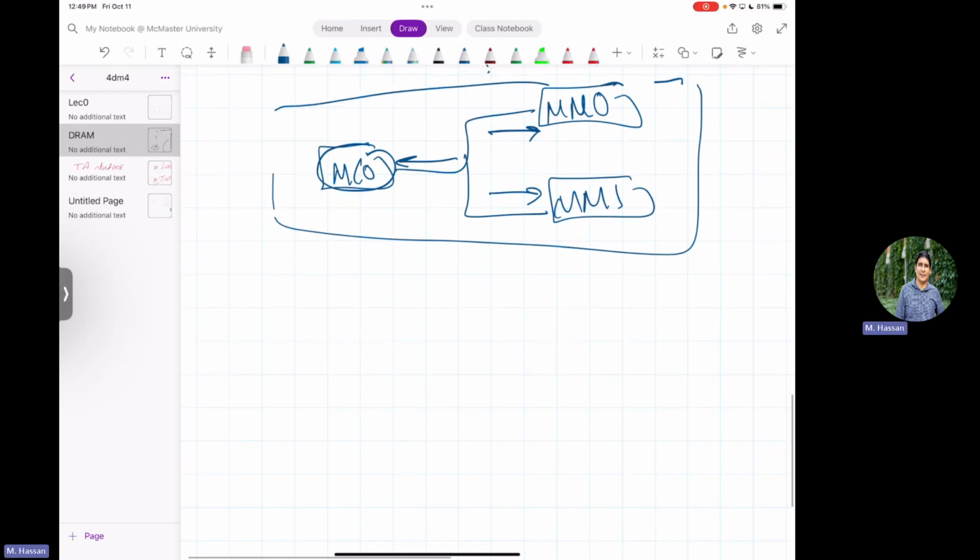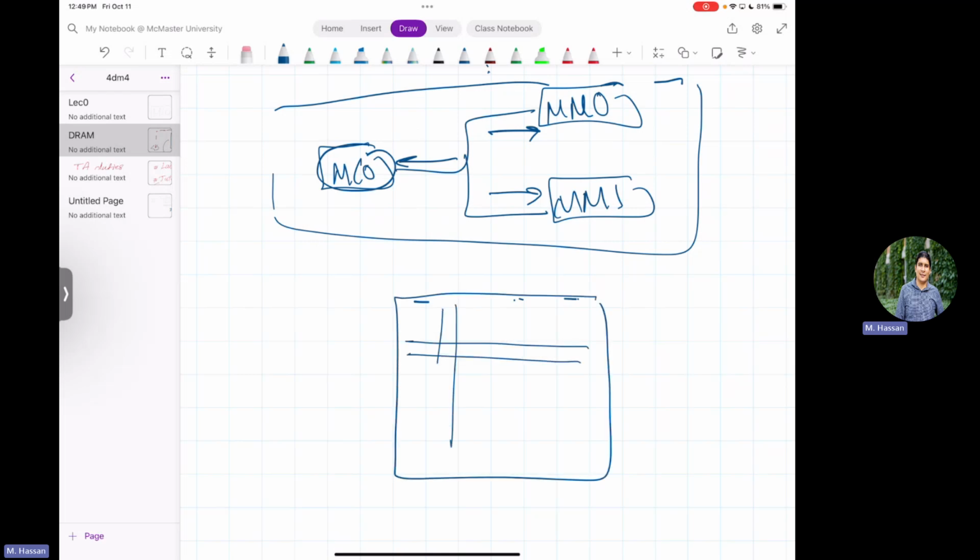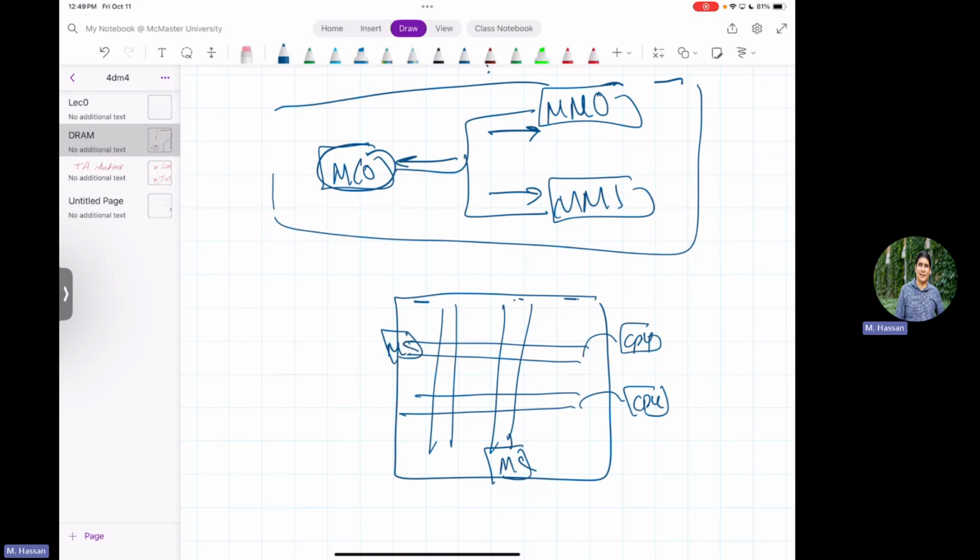In modern SoCs, where you have a distributed network and multiple chips, you might have a network on a chip, something like this. This is your interconnect, and for every router or node, you might have your CPU agents. Sometimes they put a memory controller in the far end of the chip, and another memory controller in the other far end of the chip. This allows you to connect to a memory here and a memory here. There are multiple memory controllers per chip, and this allows you to connect to independent DRAM channels.